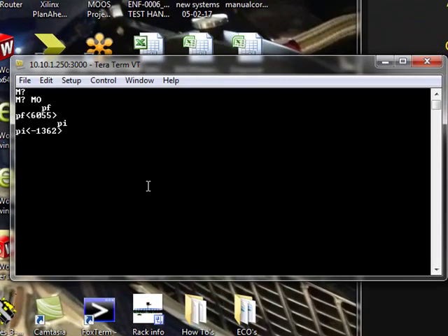For power reverse, we do PR, and this is currently reflecting a minus 70 dBm, and it's just because the power reverse is so low that it's below the measurable value. Minus 70 is the lower value that would be returned in that case.